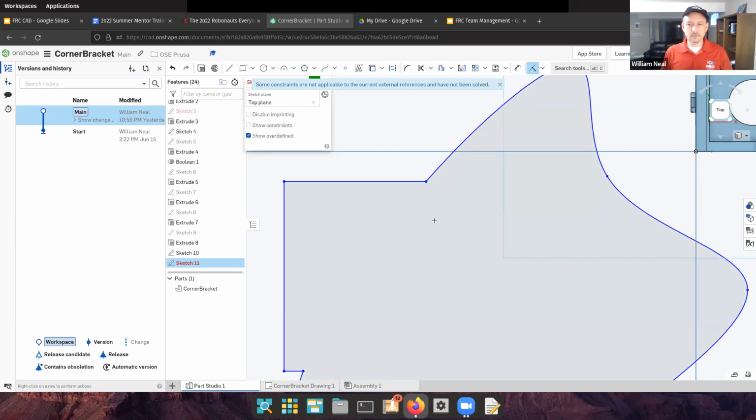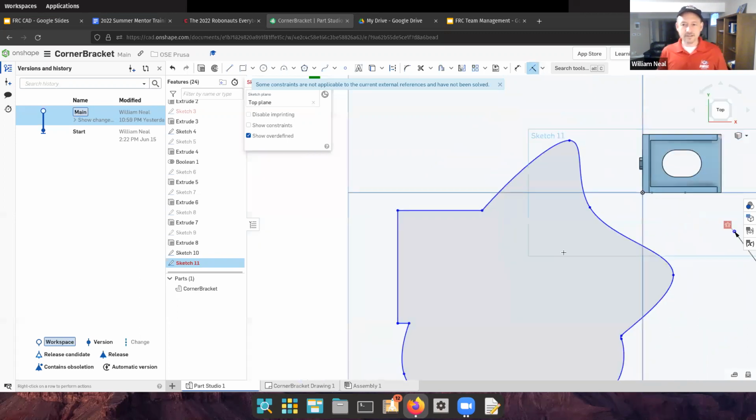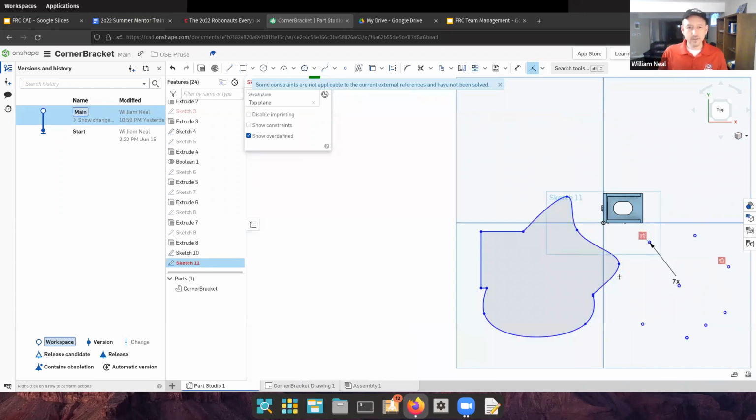And I clicked the two points and there they join together. We should try that again. I click the tool coincident. Then the next two points that I select will become the same point. There we are. And we see that I've made a completely closed loop. So that is my drawing.